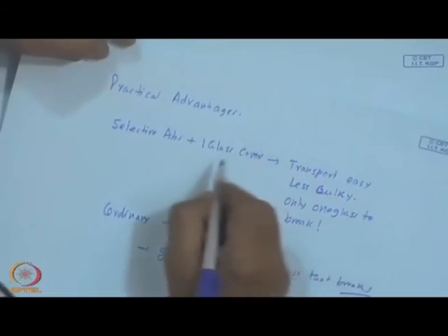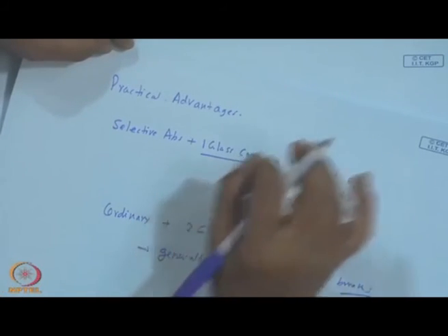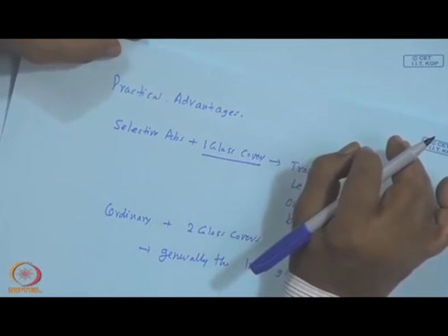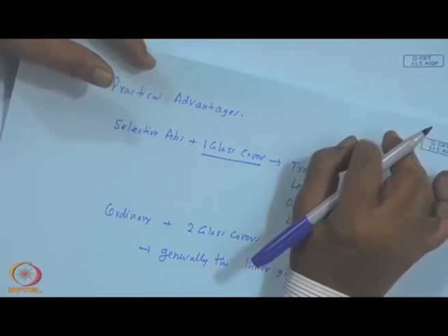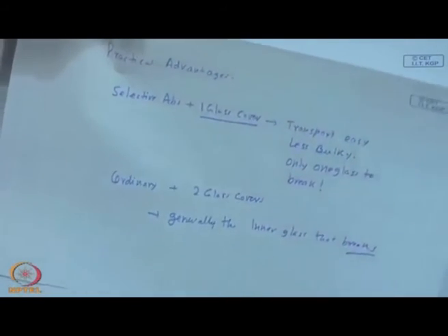So, in that process, to replace the inner glass, you have to remove the outer glass also. Consequently, it will be a little more labor intensive, and that removing the outer glass may cause damage to the outer glass again. So, in that sense, a selective surface with one glass cover, if the temperature of operation is right, is likely to be a better choice than two glass covers.